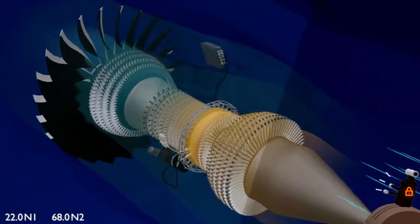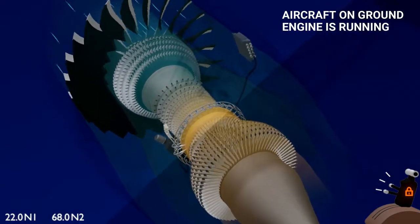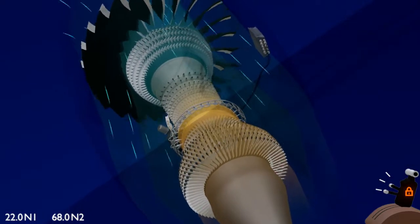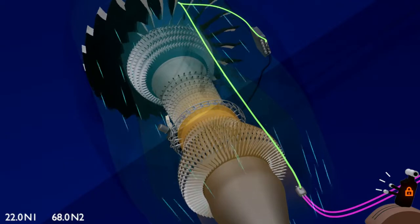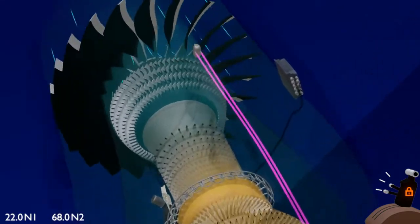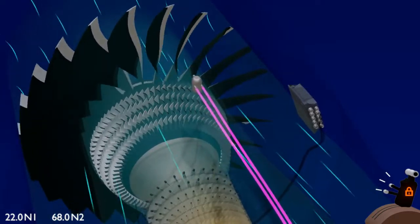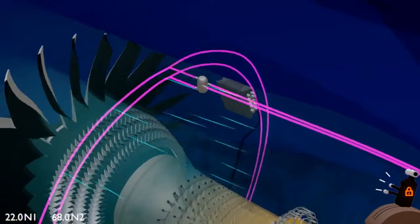The EEC operates the thrust reverser when the aircraft is on ground, the engine is running, and the forward thrust lever is at idle. Once all conditions are satisfactory, the EEC opens the reverser's hydraulic isolation valve. This sends hydraulic pressure to a direction control valve. The DCV controls the hydraulic pressure direction to the thrust reverser actuators.